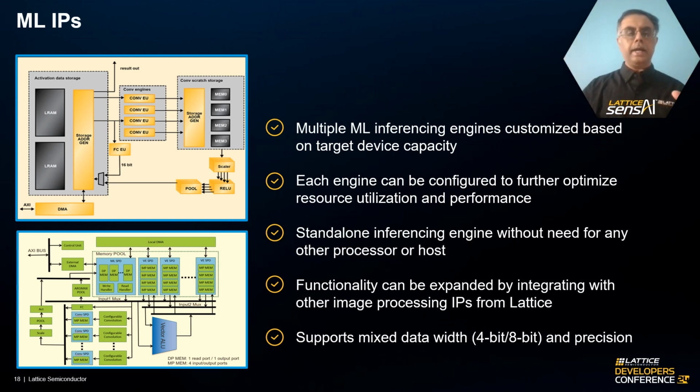So many times when you go for a very small device, the engine has to be tuned to work with those resource constraints, the number of DSP blocks, memory blocks available, and things like that. As a result, we provide various different engines. Each engine is configurable, and most of the time each engine can be targeted to more than one device. So it provides a good permutation and combination that the user can try in terms of what can be achieved.